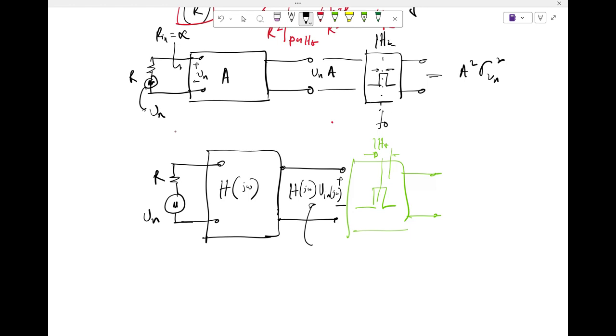I take a Fourier transform of that sequence. I'm going to get some value. I do it tomorrow, after 1 second, I'm going to get a different value, right? So this V in of j omega does not have any meaning. What does have a meaning is the statistics, right? So I know the variance here. I have sigma squared Vn will be the variance, right?